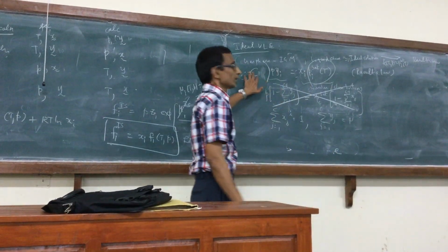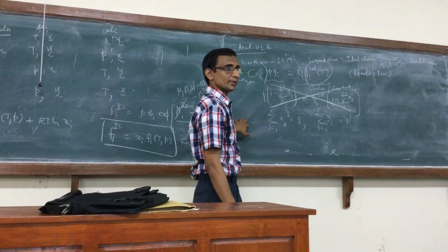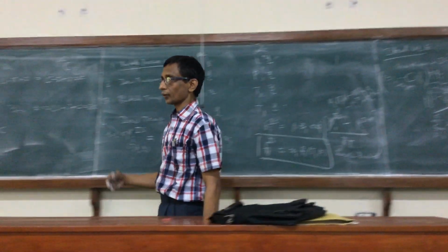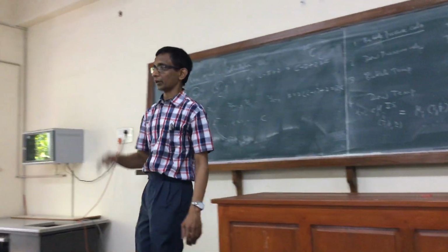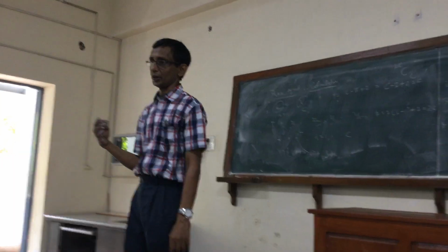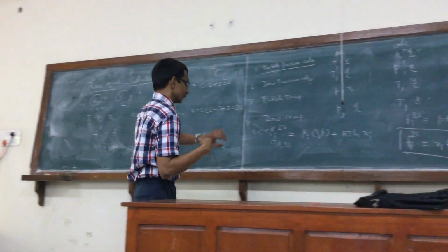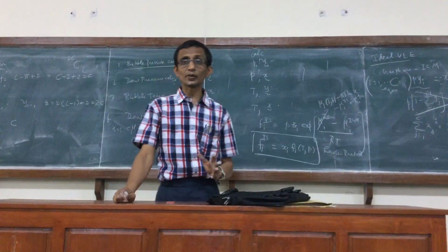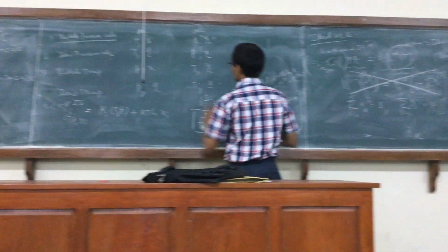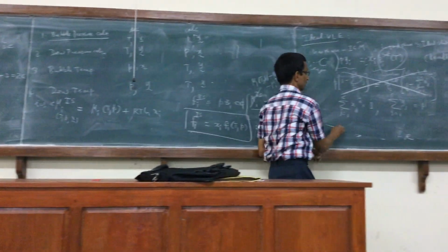Now I have C plus 2 equations, and the variables also, 2 extra variables I've added. So I keep the variables intact, the 2 mole fractions not treated as non-independent, but simply add the mole fraction constraints as extra equations. And you will see these equations will be quite important. For instance, if I take a bubble pressure calculation, automatically this will be satisfied.